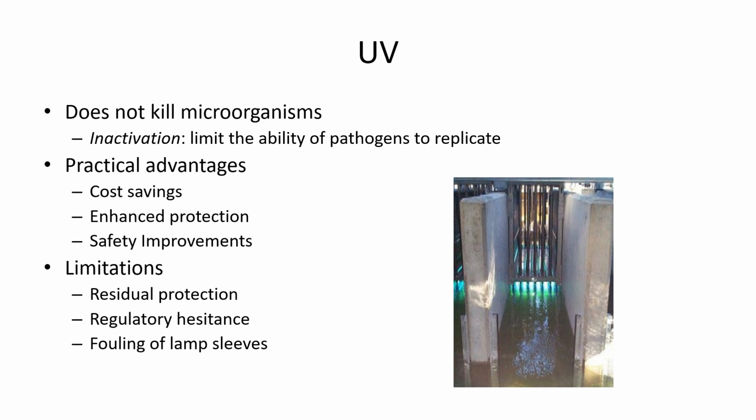UV is a special interest of mine as a drinking water disinfectant. I did a lot of work during my PhD time at Purdue on UV as a disinfectant for water and for wastewater. And the interesting thing about UV is that unlike chlorine or chemical disinfectants, UV doesn't actually kill the pathogen. It just inactivates the pathogen so that it can't replicate if you drink the water that has the contamination in it.